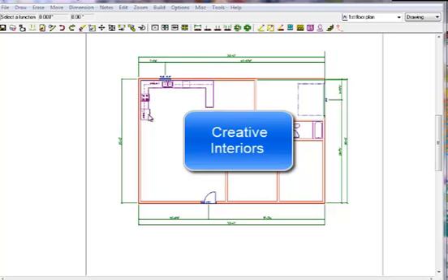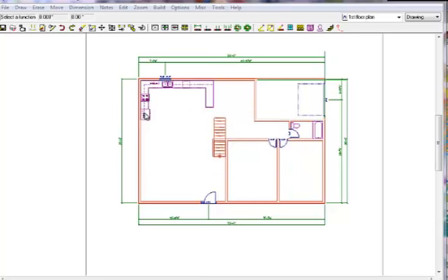the last tutorial. I put in a fridge and a stove, and I've shortened up the wall cabinets to fit around the fridge. All those things are just done using edit. In order to change and put the stove in, I did the exact same as I did with the dishwasher. I did an edit on the cupboard and then replace with symbol, and then the same thing for the fridge, and then I edited the wall cabinets and changed the height of the wall cabinets in order to suit.